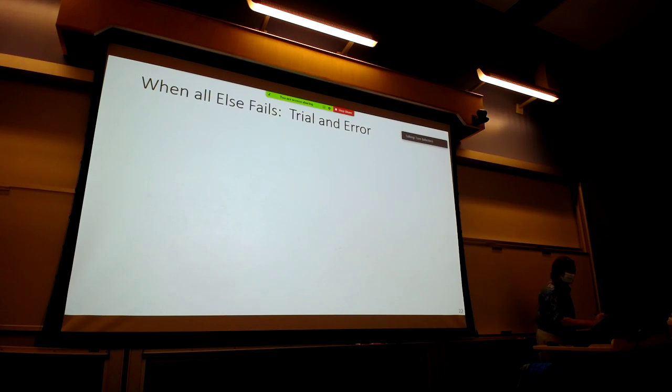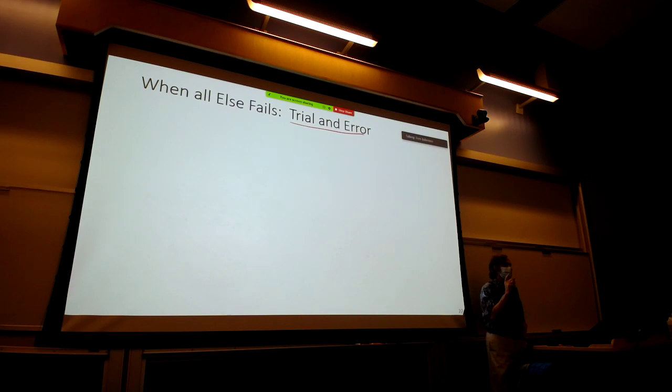So again, when all else fails, if you don't like those two methods, but remember, you could be using those methods. If you are not in the transition zone, you can't use the Colebrook and Darcy-Weisbach or the Swami and Jain Darcy-Weisbach, because those are equations for the transition zone.